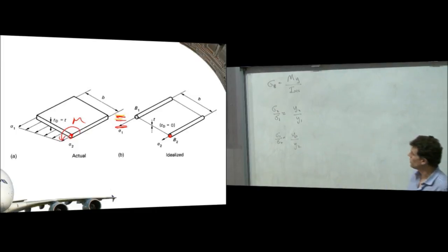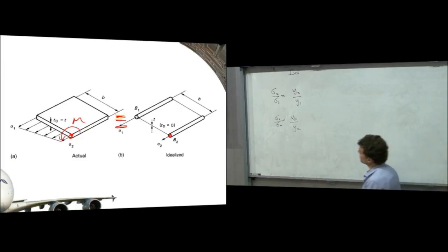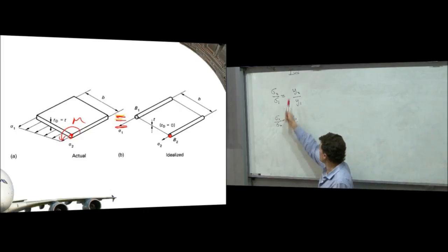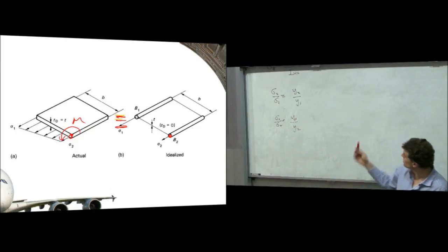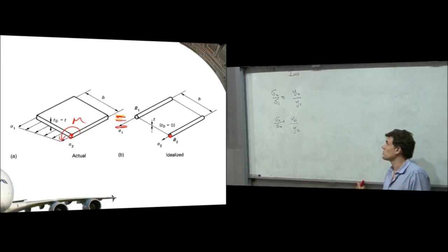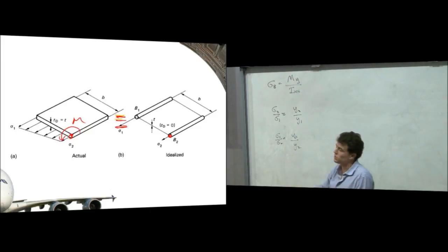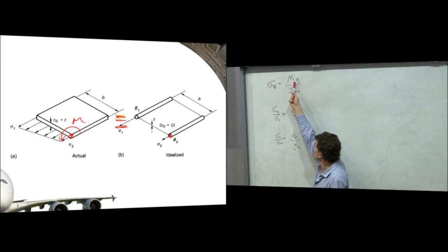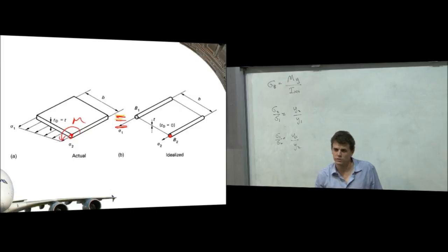okay, so for bending problems, or problems where there's just bending and shear and no tension or compression, it's a very easy thing to calculate this ratio of stresses, because the only direct stress we're going to get varies, the stress varies linearly with position. So if we take the ratio, we just need the ratio of the positions from the neutral axis.